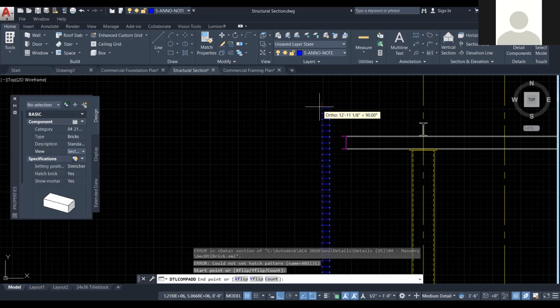It's a little high. I basically waited till the detail component manager loaded a brick in, and I erred on the higher side of the number. But I want you to give me an actual dimension. That's what I did. So the actual dimension is from the base of the slab that these bricks are resting on to the very top of the top brick, I'm getting 14 feet 5 5/16 inches. Well, that's what I have too. Okay, that's good. All right, that works. Nice.